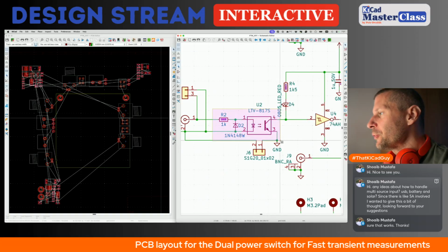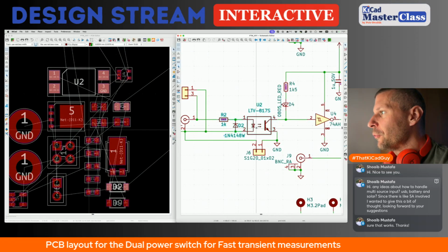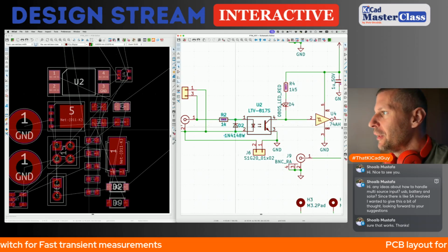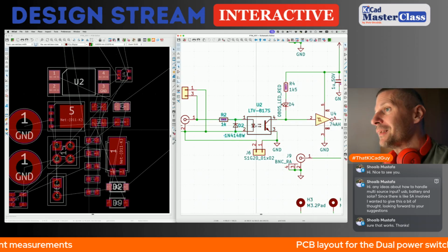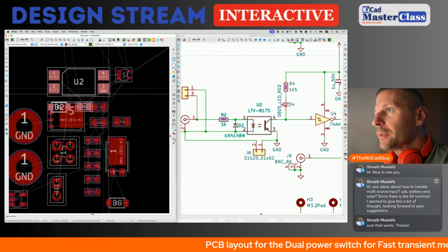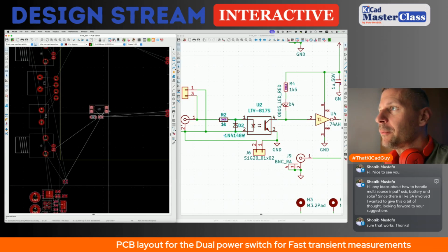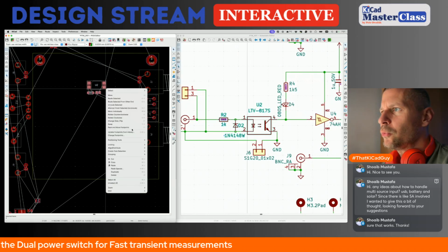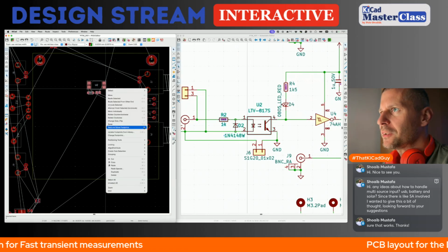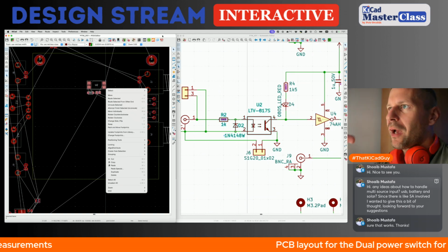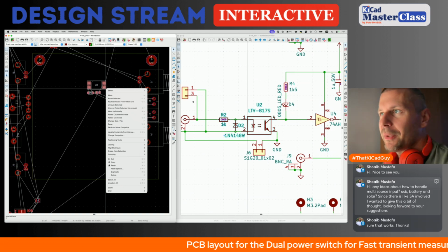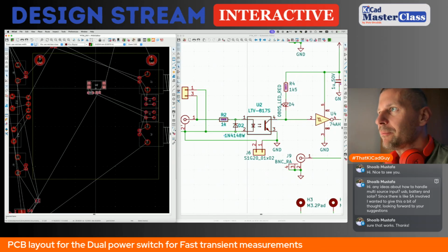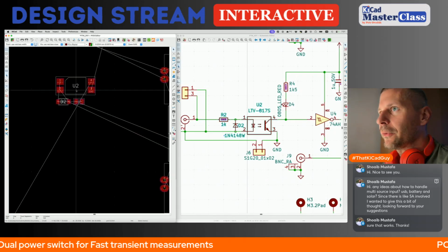So we have 3 important components for the input entry section. This is the resistor, the protection diode for the optocoupler, and the actual optocoupler. So I am using the pack and move footprint feature. By pressing P, you can grab the selected components from the schematic, and it makes a pack of them, and you can grab it and place them near your actual location.